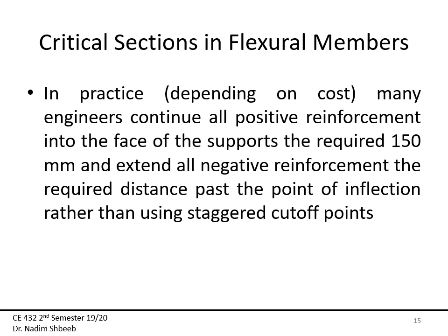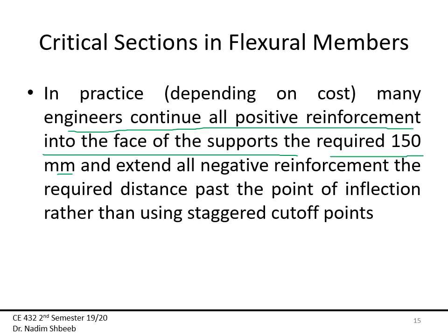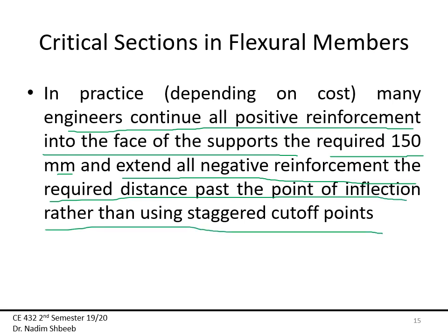In practice, what really happens, and I'm one of them, many engineers will continue all positive reinforcement into the face of the support that required 150 millimeters, and we extend all negative reinforcement that required distance past the point of inflection rather than using the staggered cutoff points. Now again, that all depends on how big your project is. Are there any real steel savings by doing this?